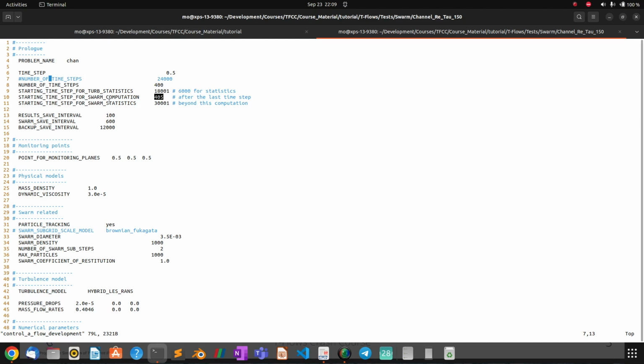But if you have a stone, or a considerably big size stone, then it will fall down with gravity because it cannot be carried by air, and it has different time scale and length scale than the carrier flow, which is the air, and then it will definitely affect the flow field. If you throw it by free fall, or with an initial velocity, then it will affect the flow field around it, which is the continuous phase, creating vortices and eddies or a wake region behind it or something like this.